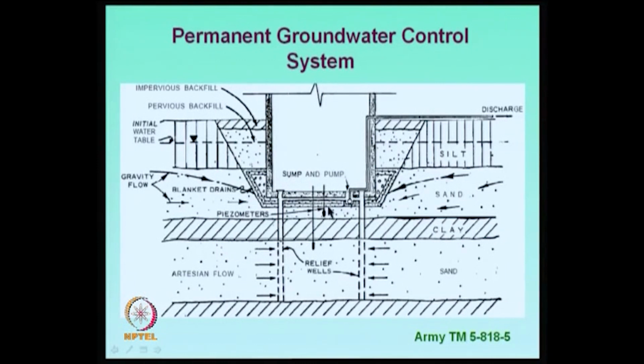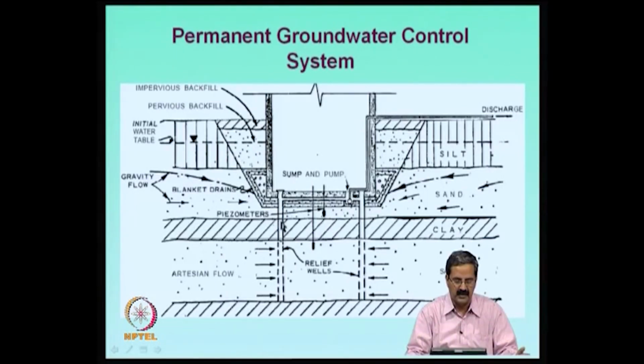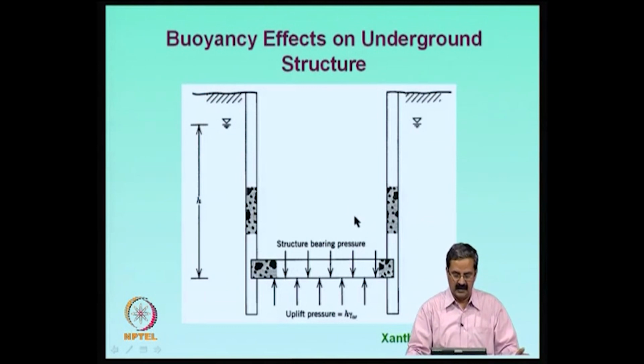There are some applications in which you try to really reduce the seepage pressures beneath the foundations, and sometimes extensive instrumentation is also placed, like piezometers. What happens is that if this is an excavation and this is the initial water level, there is a water pressure that comes in this fashion, and if you are able to release that water pressure in some sense, like passing the water pressure to nearby aquifers and also having a release system here, then it is fine. This is a typical field situation that we come across, that we should always design for. For example, if you have an underground structure, you may have to design for some sort of uplift pressures that are generated.